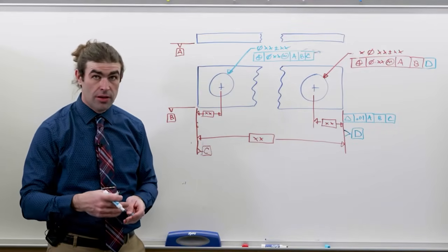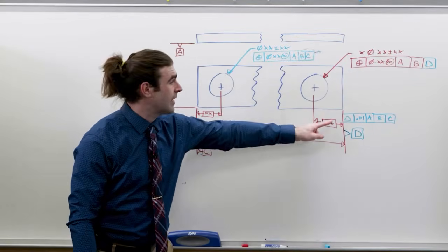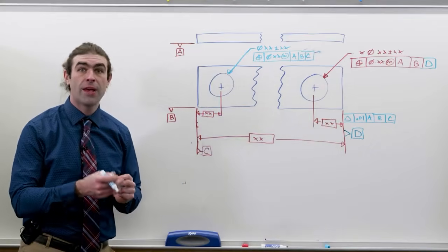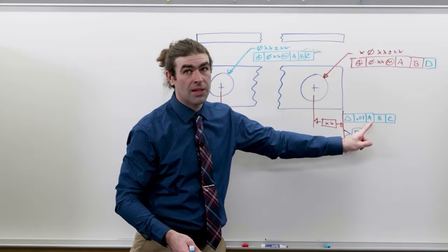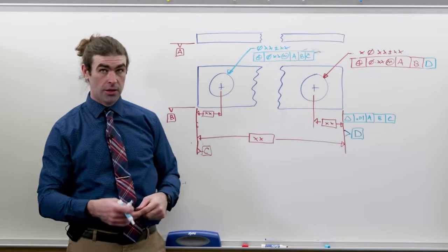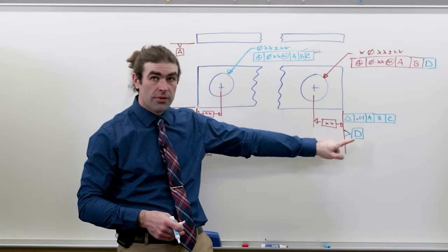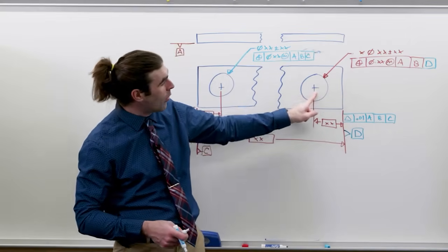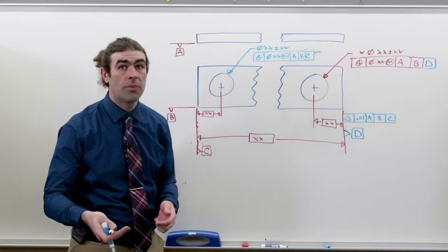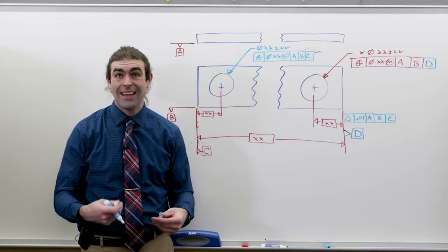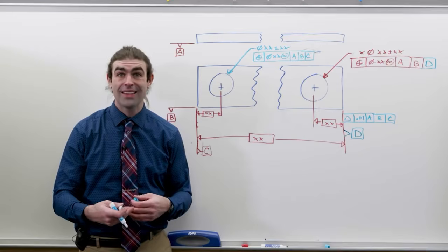We need to have a tolerance for that datum because we're using basic dimensions. We need a profile to establish the location of that surface from this side. So that profile is going to be to A, B, and C. So we're still going to have to measure that to make sure that's within tolerance. That comes and makes datum D. Now this hole can be measured from A, B, D from this side. So inspection-wise, it can be a little bit easier depending how you set it up. Functionally, this could help as well.